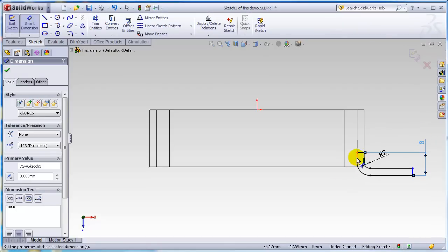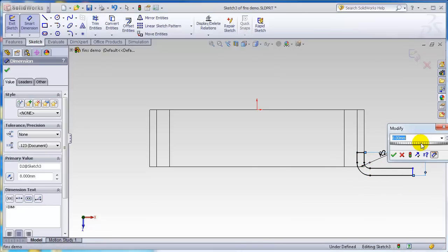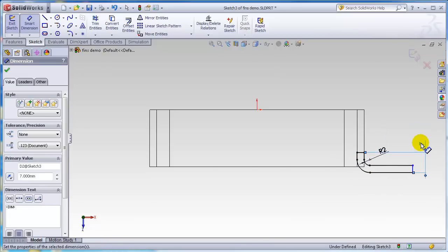That actually brings the curvature of the fin into that part, and that looks a bit more like the part that I had drawn up. And we can actually change this dimension until these straight lines almost go away. Okay, and that would take maybe a special machine to do that. I'm going to set that as a 7 just to make it look a little more interesting. Okay, so we'll make our fins look like that. That's the geometry of the fin, but I haven't set the length yet.